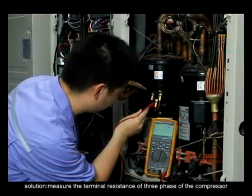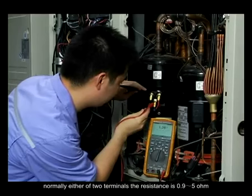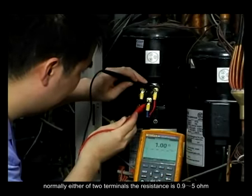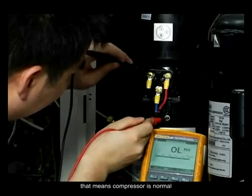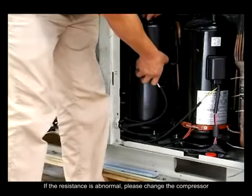Solution. Measure the terminal resistance of 3 phase of the compressor. Normally either of 2 terminals the resistance is 0.9 to 5 OHM. The resistance between terminal and ground should be more than mega OHM. That means compressor is normal. If the resistance is abnormal, please change the compressor.